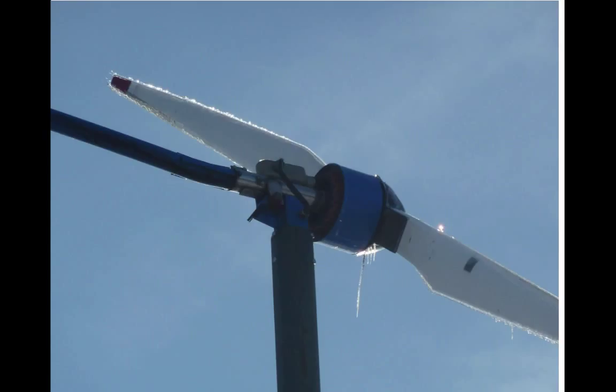And they really get beat heavily by the wind because the energy in the wind is related to the velocity cubed. So if you double the wind speed, you get 8 times the energy just blasting against that device. And then you double it again, you get 8 times again, or 64 times the original amount you were dealing with. And so the wind turbine has to be able to survive in all those conditions.